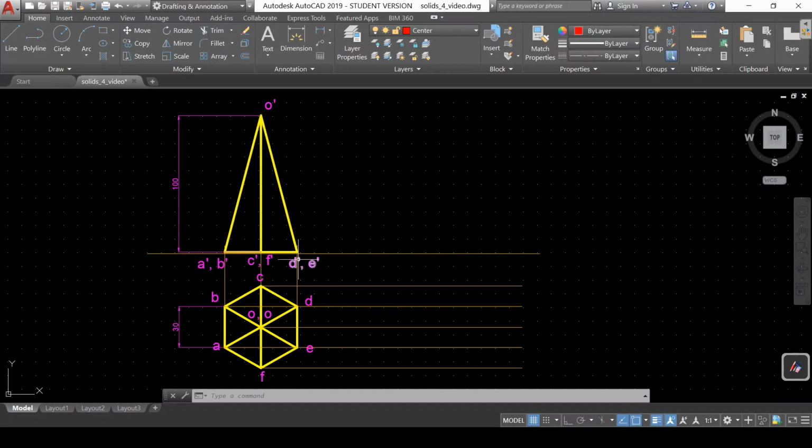Now second step, we are going to keep this edge, this is DE, we'll keep this on HP only and tilt this so that DO, this slant edge, will rest on XY or HP. So this is the second step. Let us solve this for the front view first, and then we will take the projections from the front view, and complete the second step, top view.